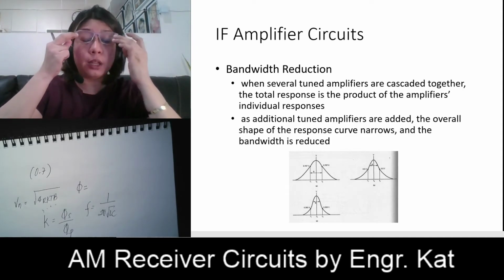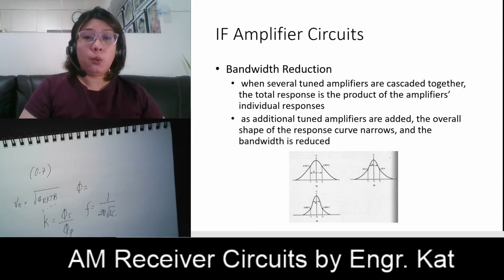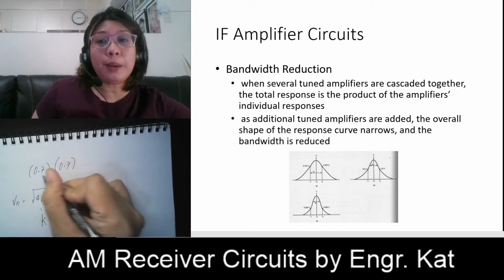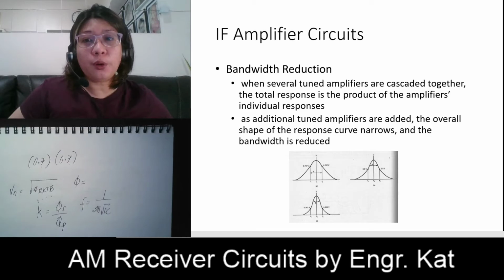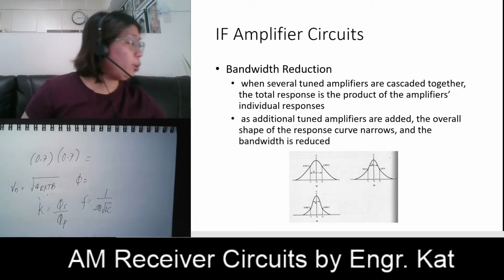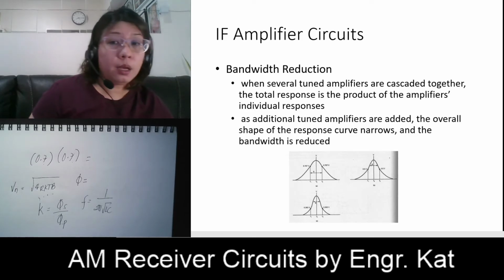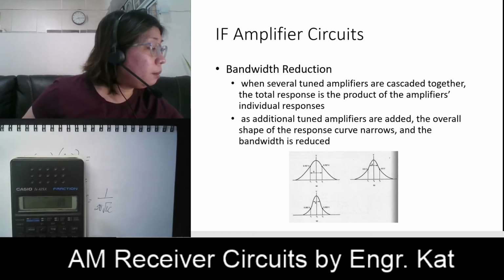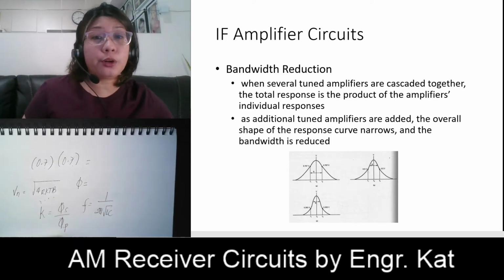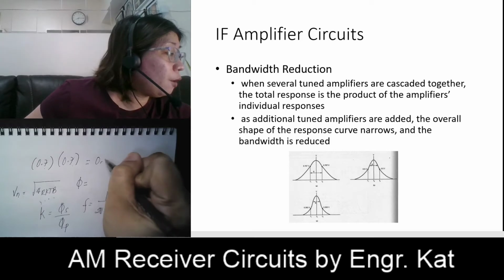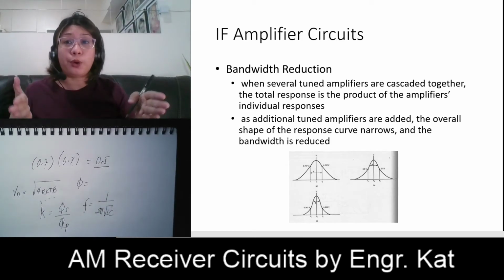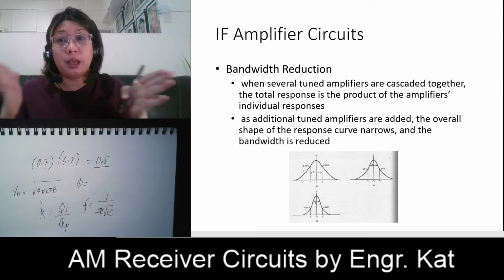So your first cutoff is equal to 0.7, while our second cutoff is also equal to 0.7. Multiplying these two, 0.7 multiplied by 0.7, is around 0.49, or rounded up to 0.5. Therefore, your bandwidth now, instead of 0.7, becomes 0.5. So it is being narrowed down.